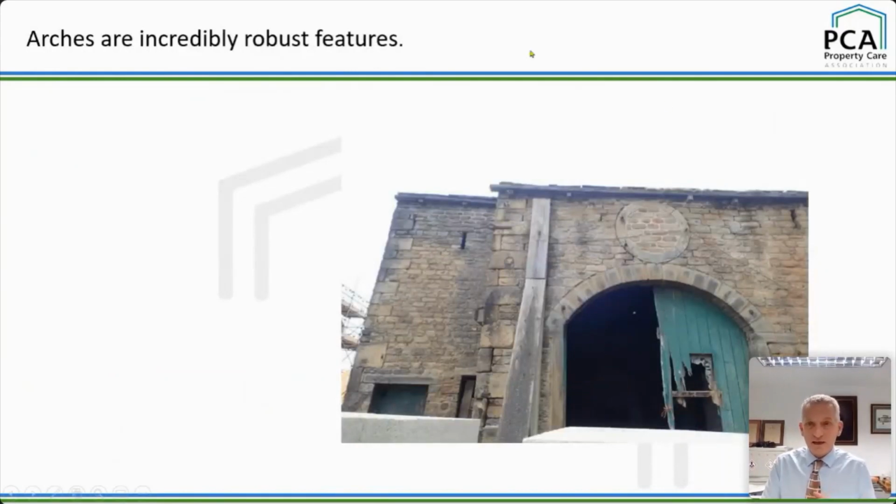Now then, here's an arch. I love arches. Arches are amazing. They're incredibly robust, right? They very, very rarely fail. This one hasn't failed even, but the abutment has failed for several reasons, okay? The left abutment's too narrow. It's not resisting the thrust here.